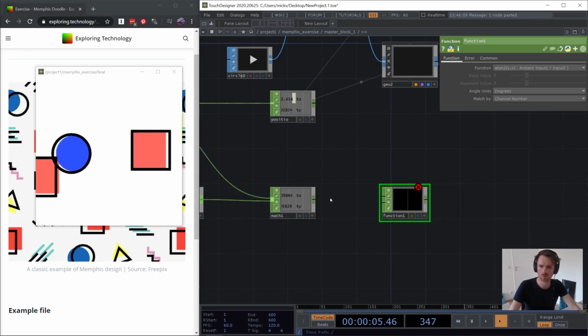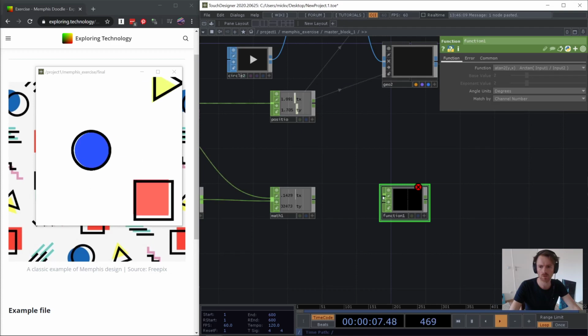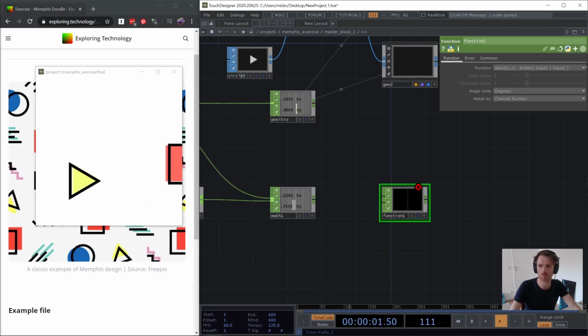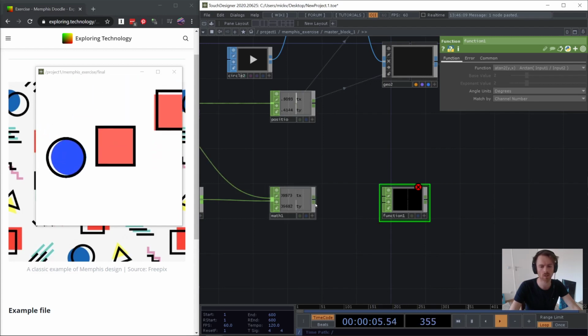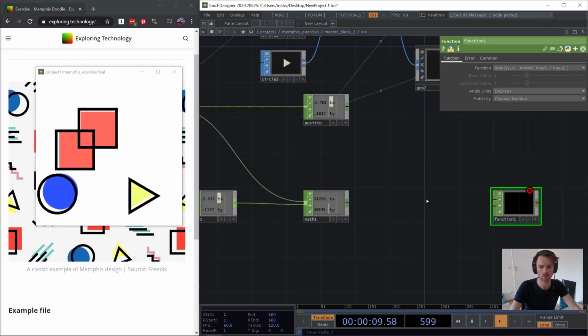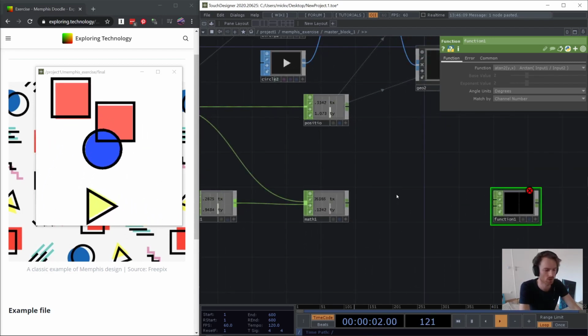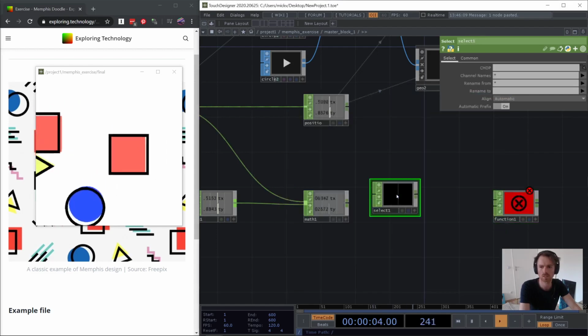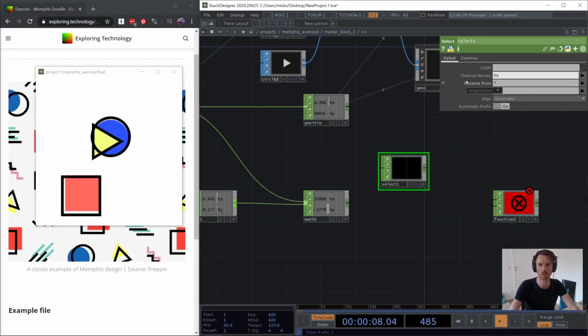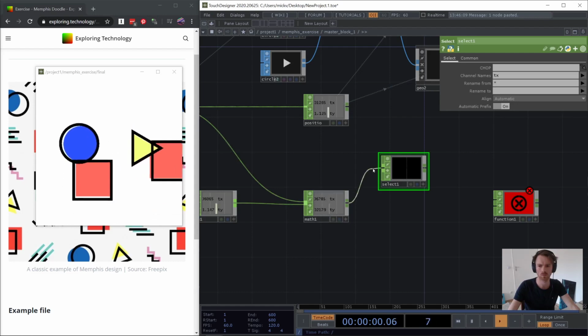Now, to put this one in here, we need to give it two values. It expects two different parameters, input 1 and input 2. And that means that we need to split these up again into two in order to be able to feed them into this function. So just as we've done with the first example, we're going to use a select, and we're going to set this to tx and hook it up.